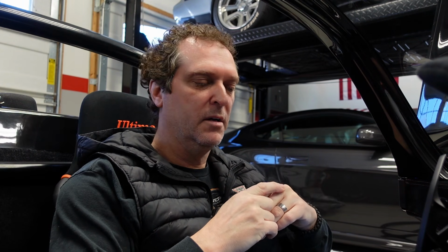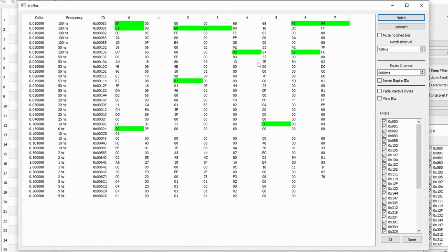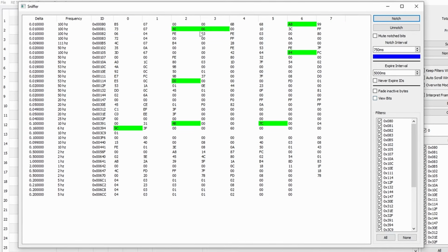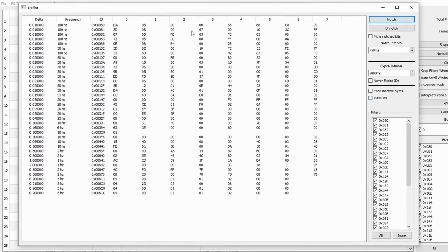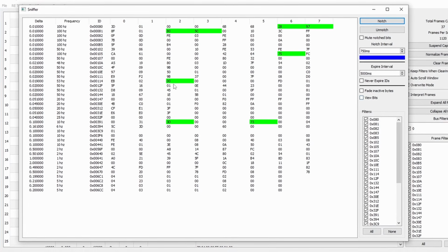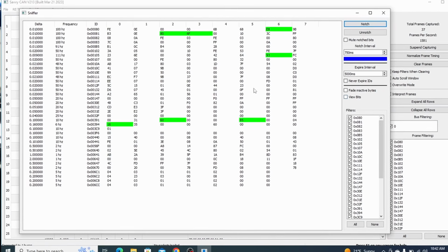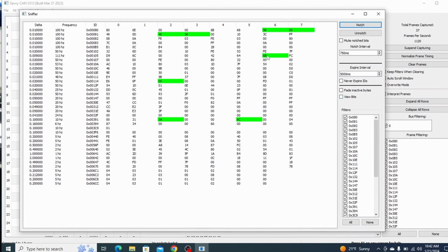The starting value is 0, and the maximum value is going to be hexadecimal starting with F, 0xF, either FF, FA, something in the very high range of the hexadecimal values. So let's look for that. Again, I'm going to hit the throttle, 3, 2, 1. And I'm looking, it's definitely not going to be two bytes spanning across. So the top row, we're not going to even worry about. These aren't really changing when I press the throttle variably. But one I do see is right over here.